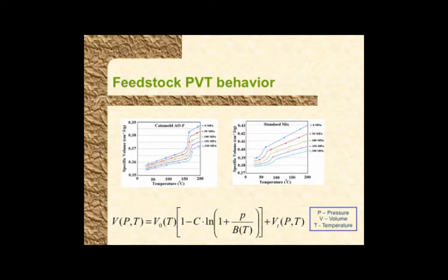From a process design perspective, as an engineer, you need to know how these properties are changing, how is shrinkage changing, how is density changing in the mold cavity, because you will get parts with different weights. And then if you remove the polymer, they're going to shrink to different extents, and you cannot control the precision.